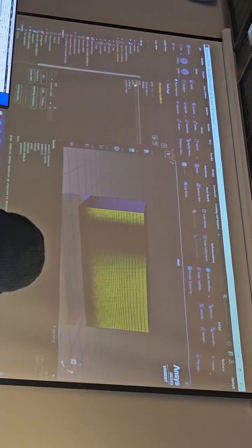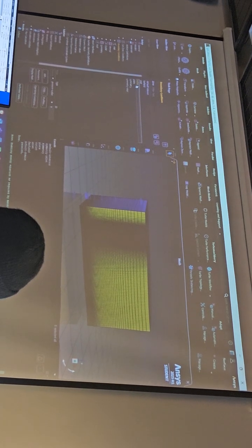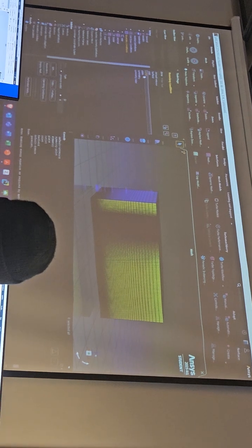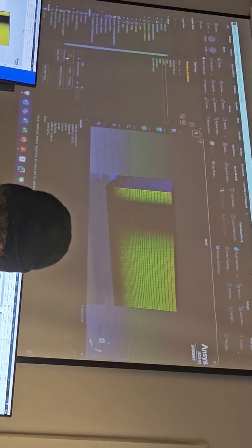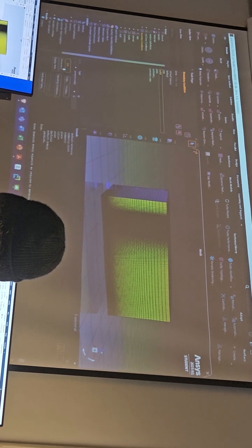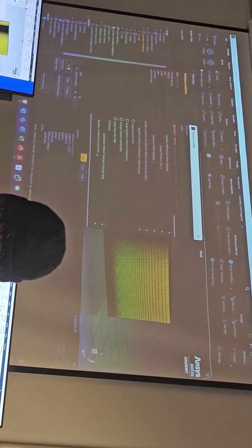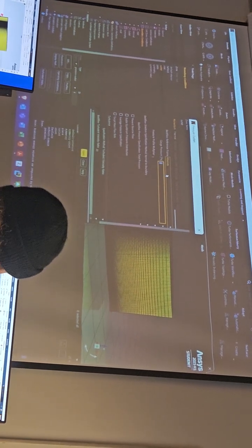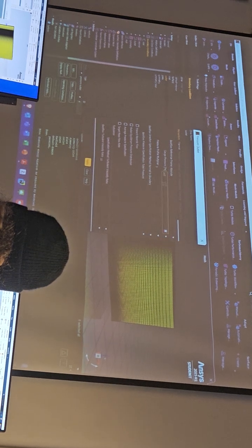Then the next boundary condition that we need to set is at the outlet. So we have a static pressure at the outlet that is 1 bar. This is already a pressure outlet type, but we need to change the magnitude of the static pressure. So we edit it, and the gauge pressure, this is still in Pascal, so it's 10 to the power of 5, that is 1 bar.